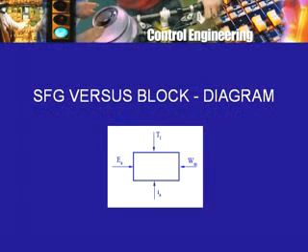It shows all the things fairly explicitly, whereas earlier we just drew a simple block and I put there the words motor and load, and I showed two arrows going in and two arrows coming out, and at that time of course I showed EA and TL as the inputs and omega m and IA as the outputs. So if I just draw a block like that, it only tells me that I am going to look upon these two quantities or variables as my outputs and these two quantities as my inputs. So I am going to think of in this way, that these inputs may change, they will in turn cause change in the output, how much, etc. The block diagram itself does not give you any further information.